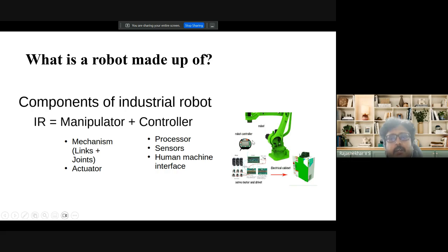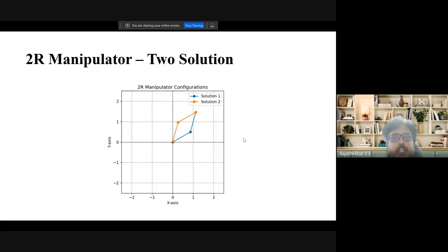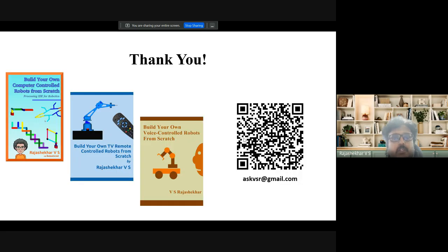But in autonomous mode, the robot tries to find the shortest path it can take, and it tries to go to the joint angles which are closer to it. So that is how it is done, using the shortest path or the energy consumption. These two things are taken into consideration, and the six-axis robot works this way, using the 8 solutions it has.